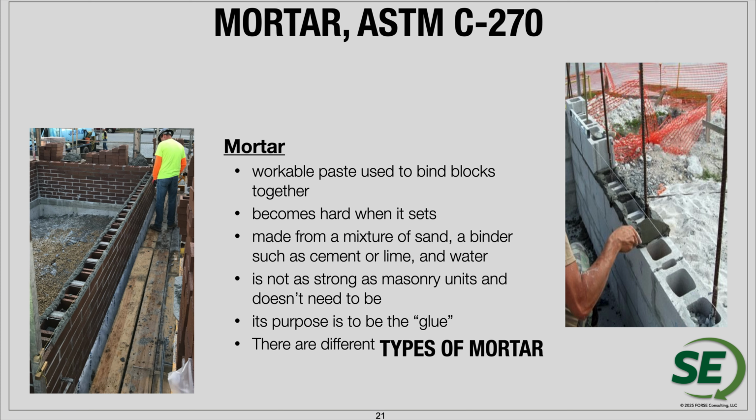Mortar is really going to be that cementitious material that we're going to use to bind together the units. So it's going to get hard after it sets. It's going to be made up of a mixture of sand, a binder element such as cement or lime, and then water. When we test the mortar in isolation, the mortar is not going to be as strong